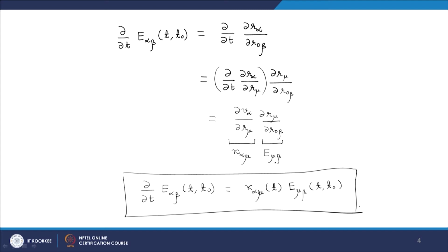So, now I want to take this idea further on how it is ultimately useful, because we have reduced the problem of working in terms of the stress tensor to working in terms of deformations, but we have not yet said how we will relate the stress tensor to the deformations. And the answer here is looking at free energies of the kind that we have discussed while doing the lattice models of polymers.